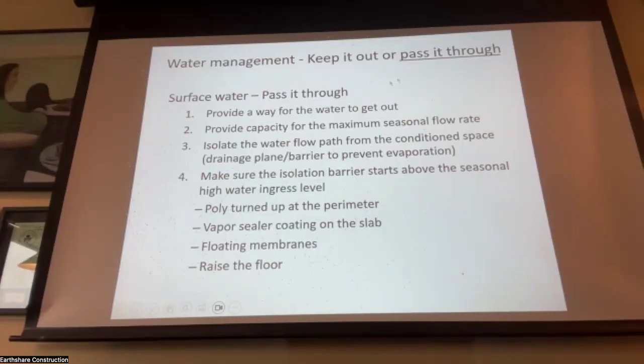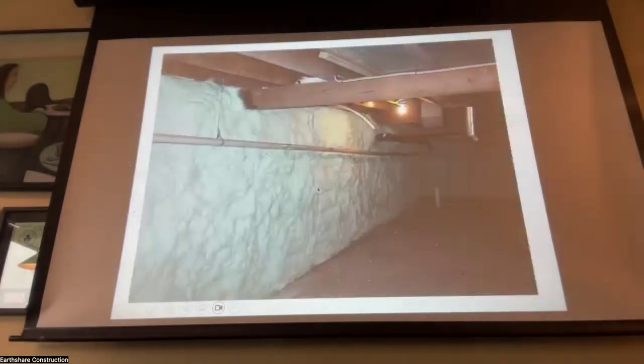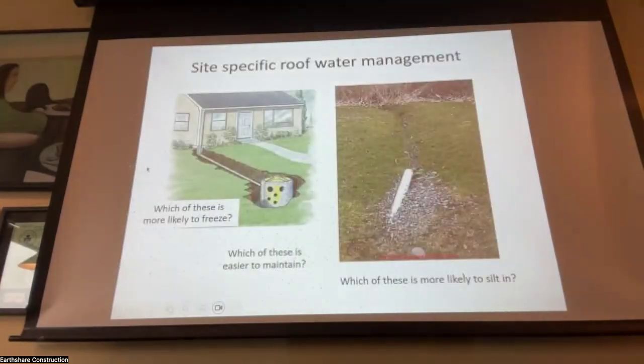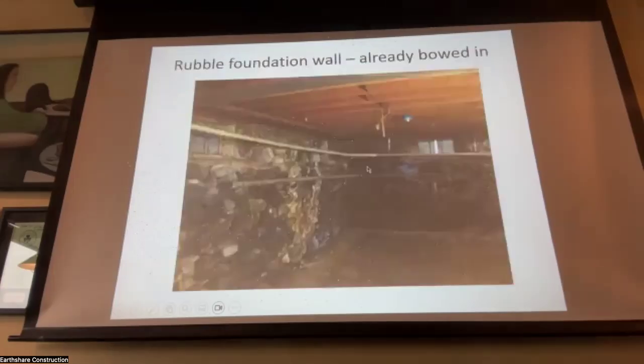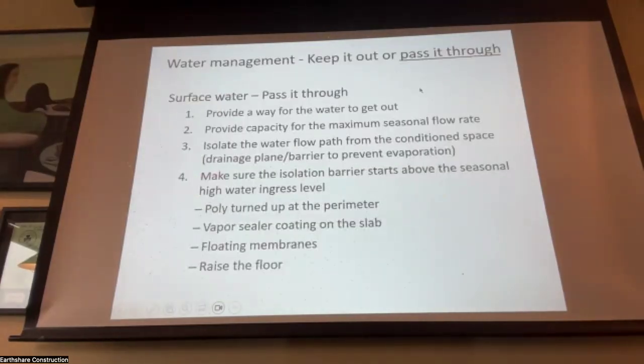And I'm here to tell you, you can't make the grade impermeable. You'll never guarantee that no water will ever get into the foundation. You're going to assume it's always going to get into the basement.